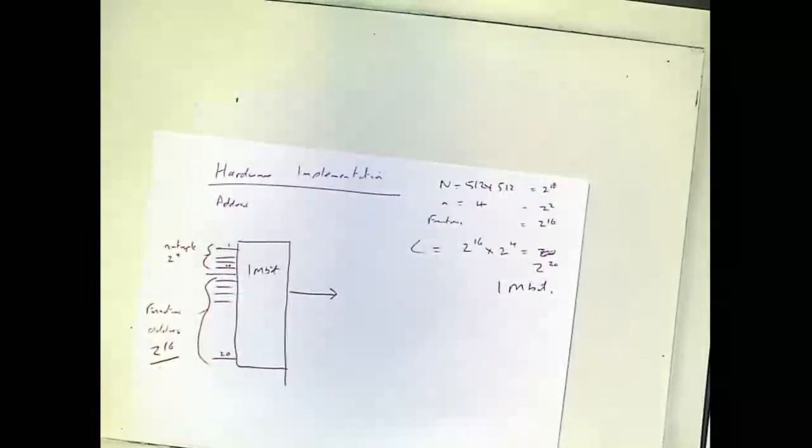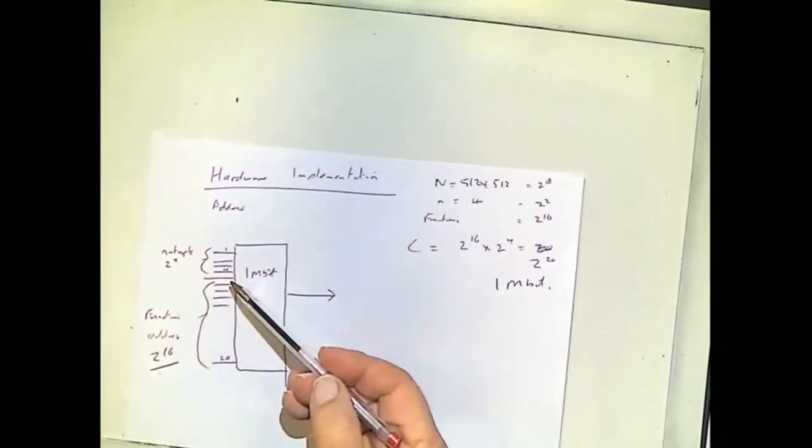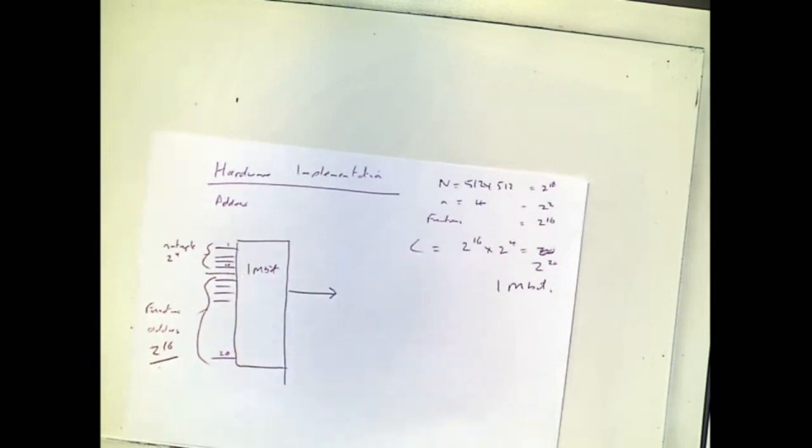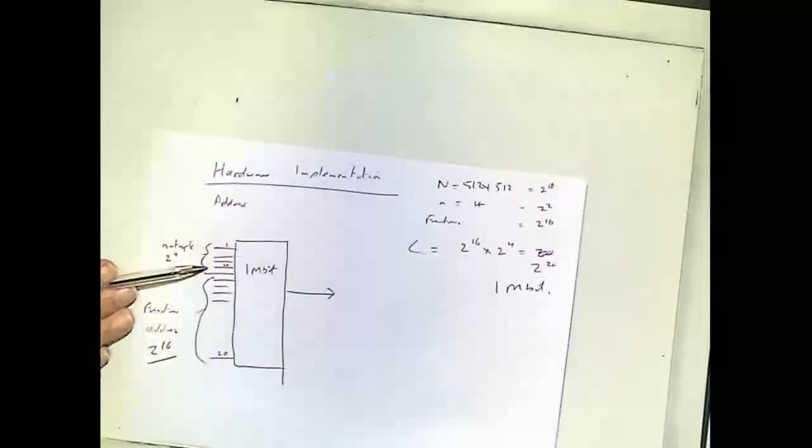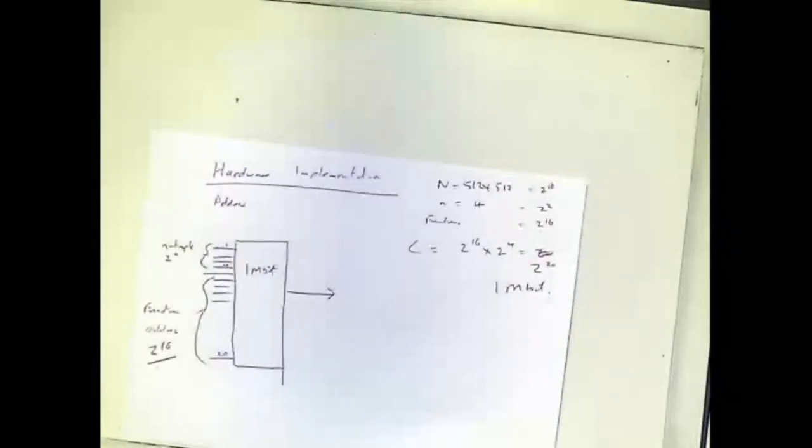And how do I access those functions? For the very first function, the inputs are on the n-tuple lines, A, B, C, D, coming in there. Set the whole function address field to 0. It will only address one of 16 bits in the memory, and those 16 bits will depend upon the inputs of the function, A, B, C, D, and all the rest will be 0.